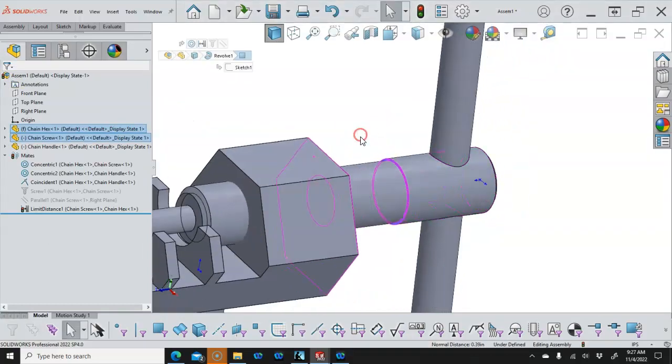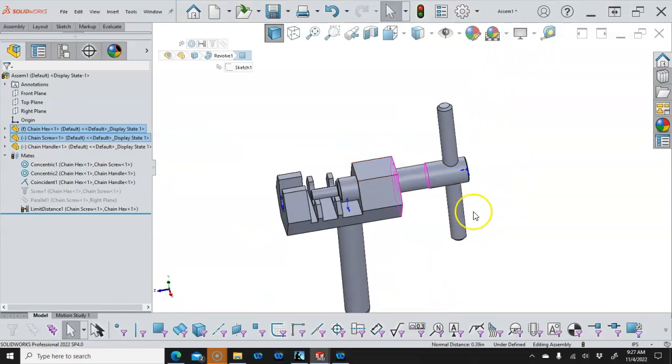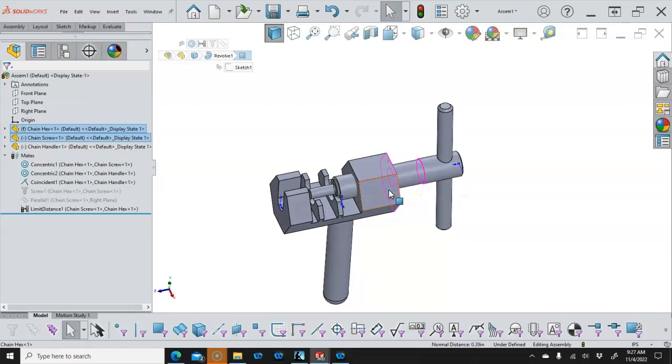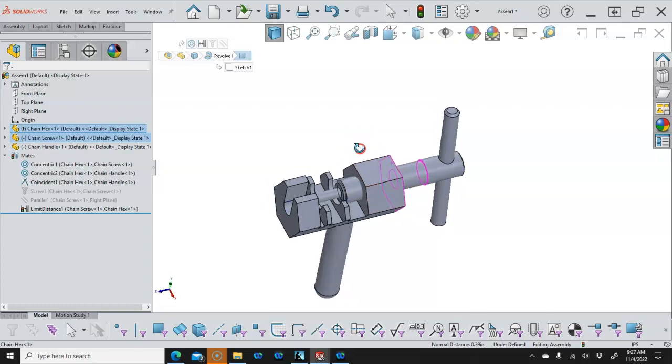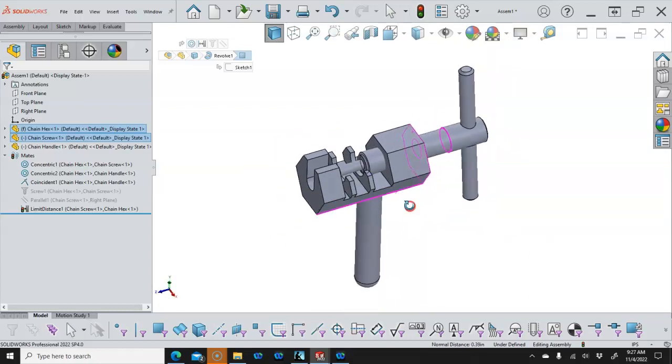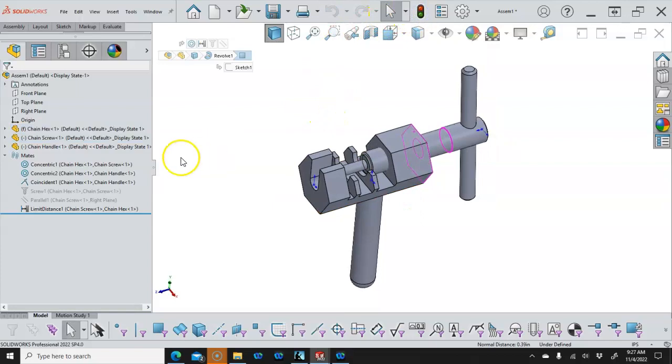So really we're about 3/8 longer than we need to be, other than keeping your hand away from the hex. I think the engagement's good there, 5/16 to 1/2 inch across those faces, about 1.5 times the diameter of the screw. So mechanically that should be pretty good.